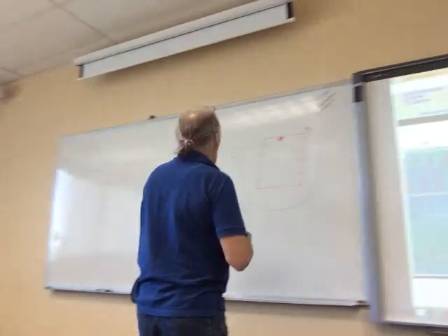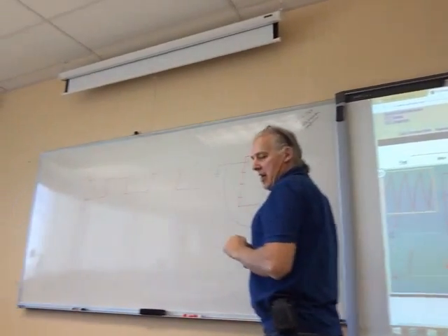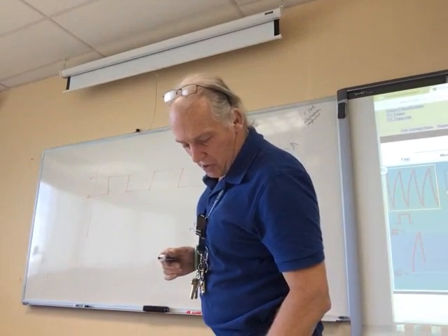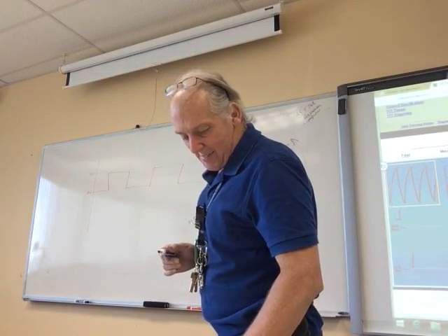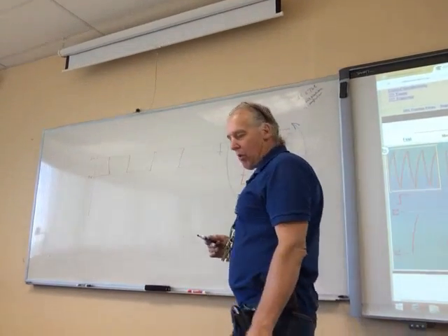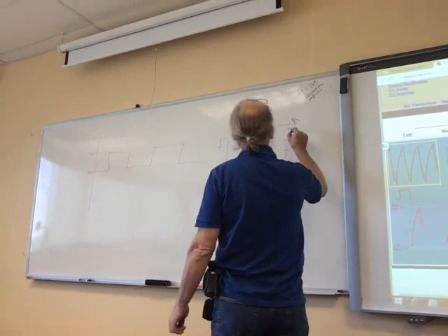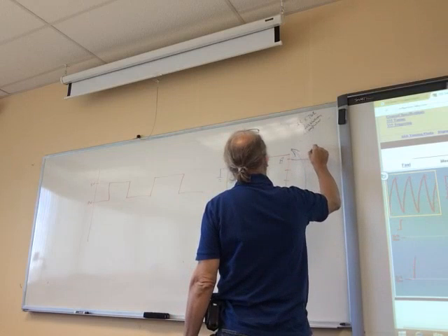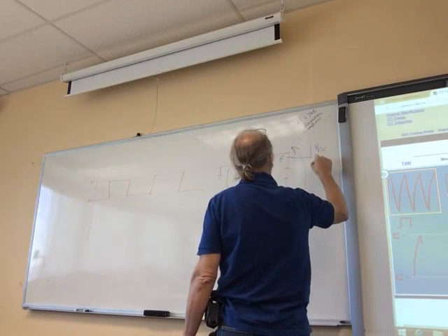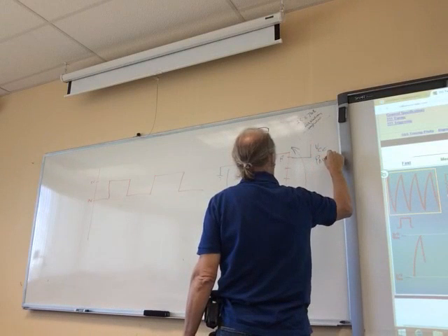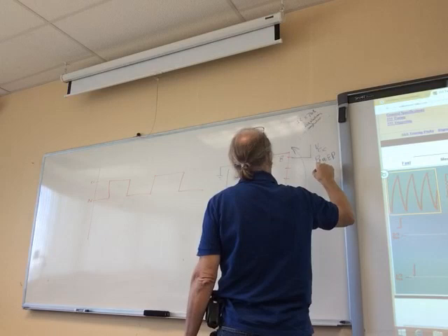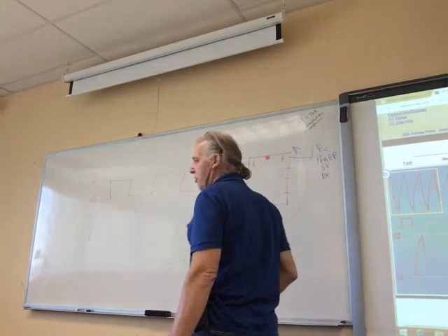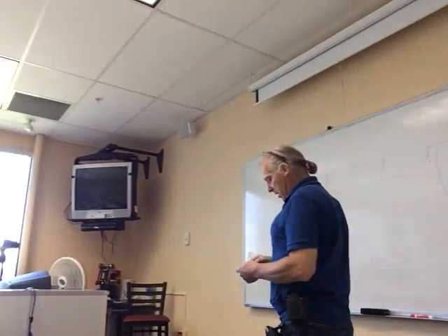All right, so pin 1 is ground. If you look at your picture, you'll also see pin 8. I know pin 4 also is connected to VCC, but pin 8 is VCC. And what is VCC? Power. You are correct. And that, for us, is 5 volts DC, and it has to be on a regulated circuit, okay?